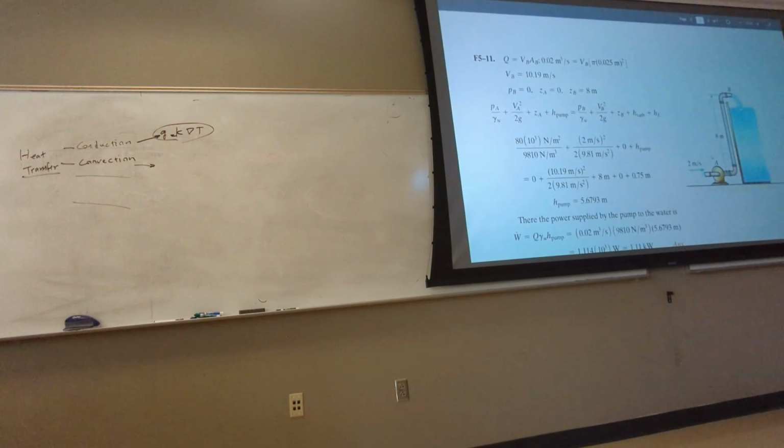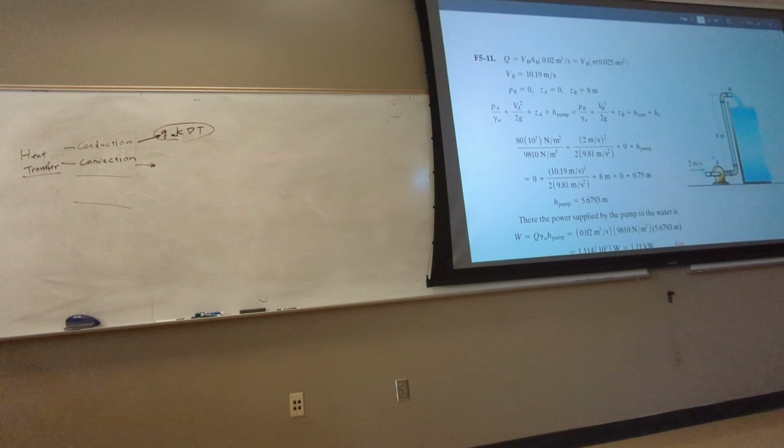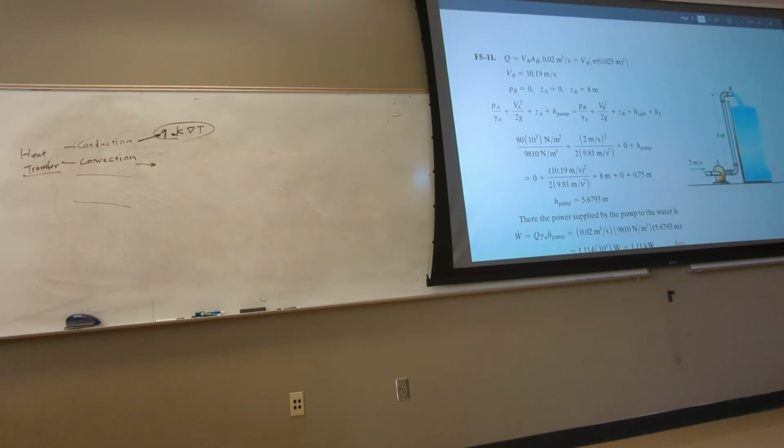It's not very intuitive. But if you do it once, which we did in fluid statics, hydrostatics, then we realize, oh, it doesn't matter that the gauge pressure, whatever it is, atmospheric pressure, P0, you cancel out whatever you have. So you only have gauge pressure, 0 here, and then you have ZB in this equation. There's the height at B, which is 8 meter. Now you could choose this point as a reference. Then if you choose this point as your reference, your ZB is what? 0. What about ZA?